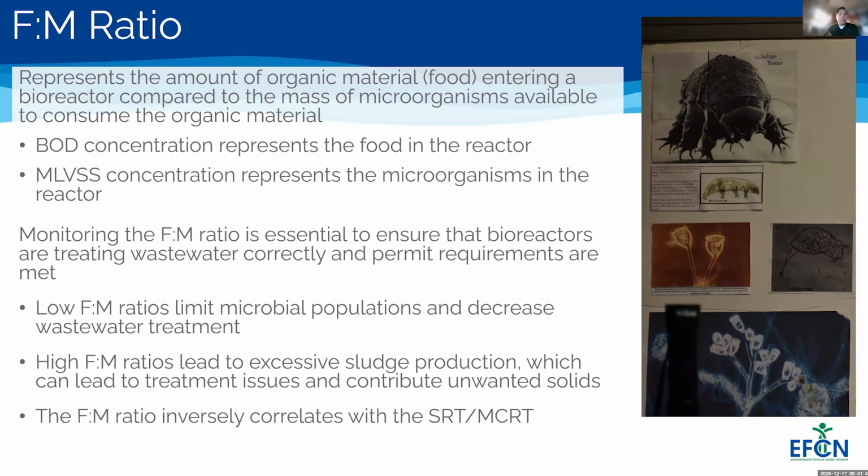The BOD is the representation of the food in the bioreactor, and our MLVSS is the part of the equation that indicates the microbes. Monitoring our F to M ratio is essential to ensure that the bioreactor is treating wastewater correctly and our permit requirements are being met.